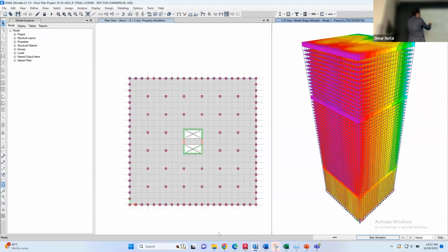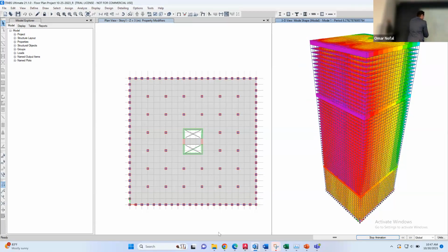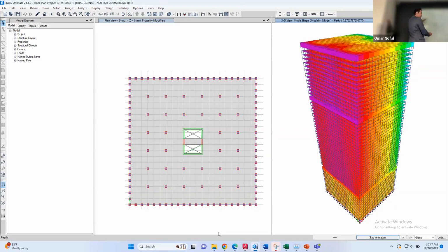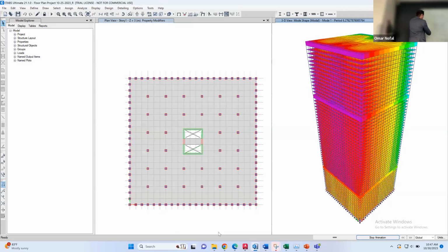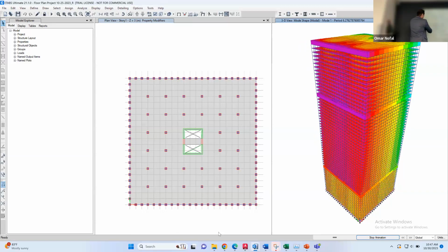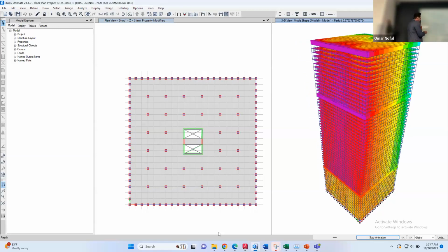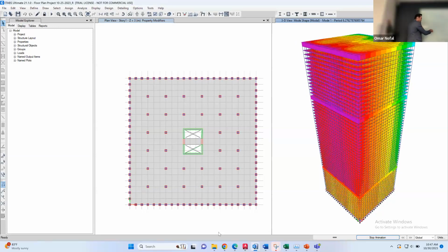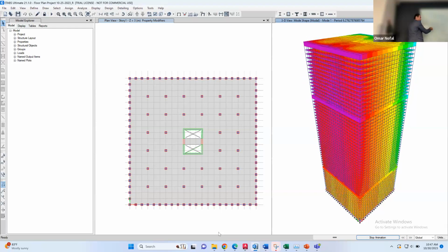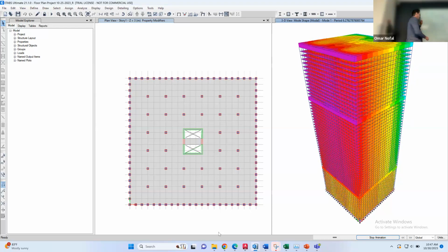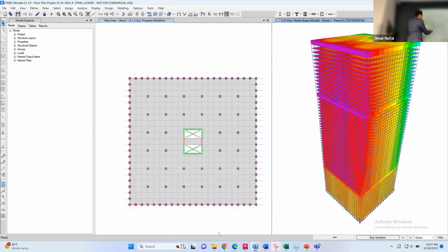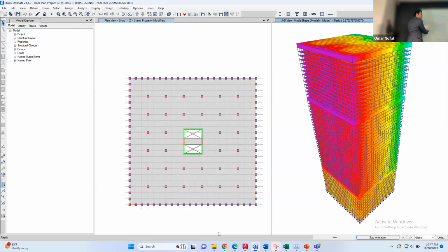Let's assume this is your building, okay? You are going to visualize the building in the XZ plane, and you have something like this. And let's assume the new outrigger is here. So when you do the bracing, it might get here. It doesn't have to reach this point. It's better that you connect. It's better if you were able to. The thing is, the bracing needs to connect columns, right?